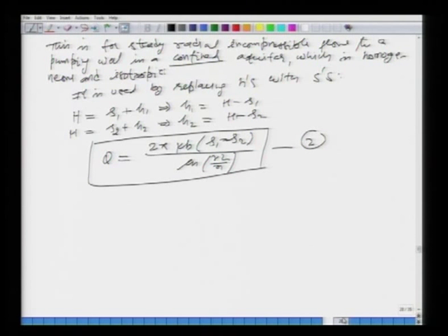Okay. All right. So, now how can you find out this S1 and S2? Well, basically you have the observation wells, and then you find out the distance between the groundwater table and the current groundwater table under steady state conditions. All right. That is your drawdown. Now, further we can use this equation on the boundaries or the boundary conditions. Okay. If you do that